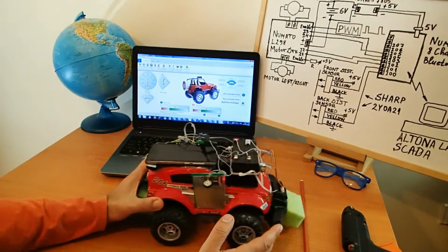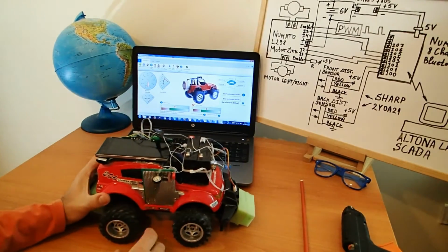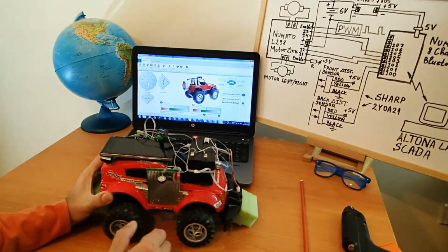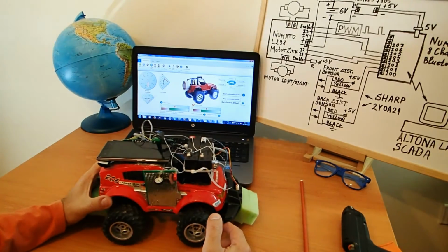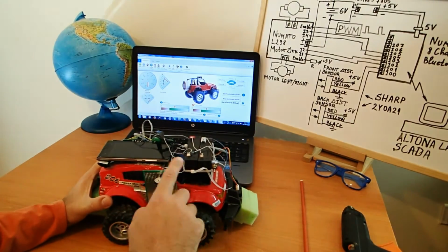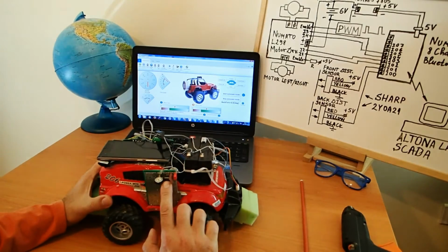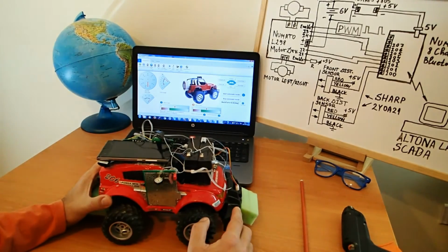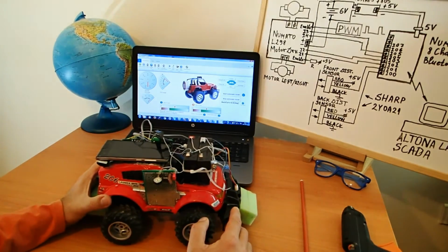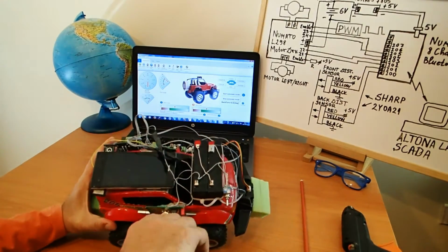Because the car is very fast, we have to reduce the speed of forward moving DC motor. For this purpose I use a pulse-width modulation with 555 integrated circuit. It is connected to enable signal of the DC motor driver, and I experimentally set the needful filling factor of the impulse.